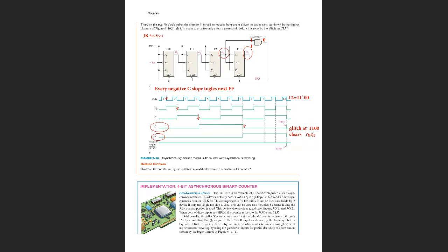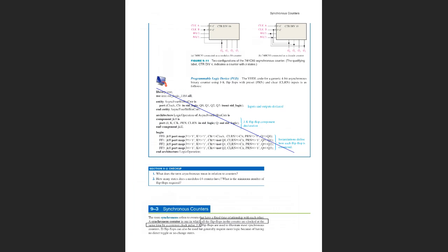because flip-flops FF2 and FF3 become 0. By the way, when you look at FF0 and FF1, those flip-flops are not cleared. They are never cleared, only Q2 and Q3 are, which prevents the number from becoming 12. Instead of becoming 12, because of this glitch, because of the clear signal, they become 0. The whole counter is reset to all zeros.